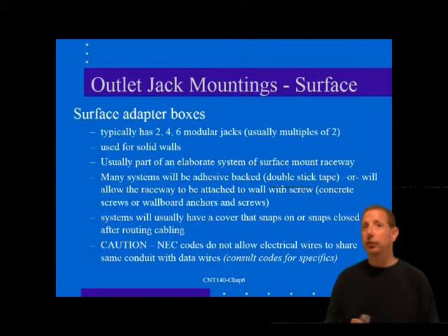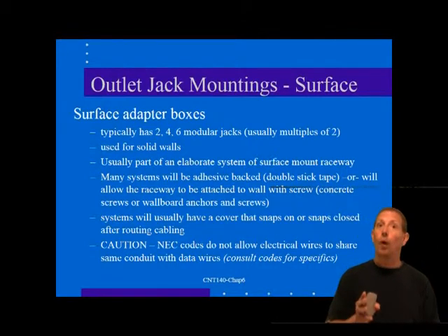A note of caution should be stated regarding these raceways and matching boxes. The safety standards of the NEC and other agencies do not allow telecommunications wiring to share any raceway space or outlet box with Class 1 wiring. Class 1 wiring is wiring for lighting or electrical power circuits, the typical line power that supplies lights and electrical outlets. In some narrow cases, the wiring may be allowed in the same outer raceway cover, but it must be separated by a specific type of partition.